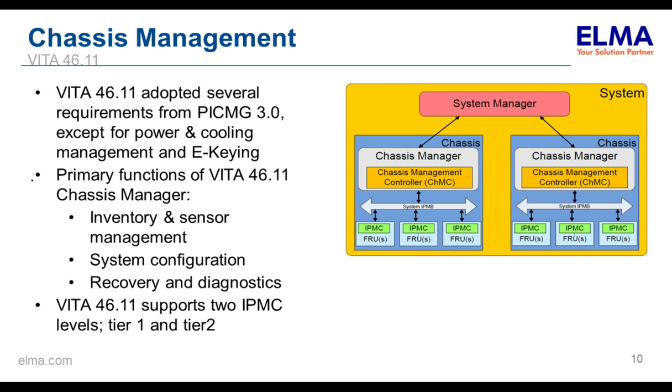The primary function of the VITA 46.11 chassis manager is to inventory the boards that are in the system and to manage the sensors within the system, to do system configuration and recovery and diagnostics in case of any failures or faults.